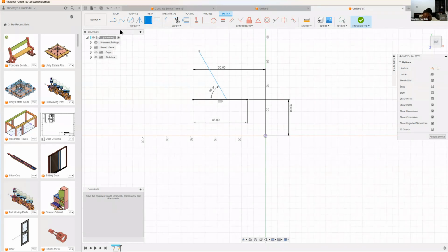I can put other pieces of information, like selecting what that edge point is. If I do a dimension now, and I choose this edge, and choose the beginning here, let us say I make that 70. And then take that point again, and choose a horizontal distance from here. Suppose I make that 50.